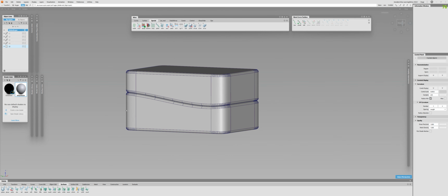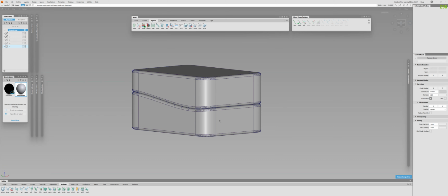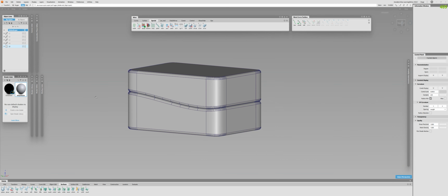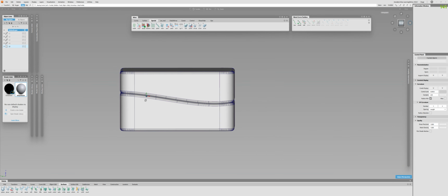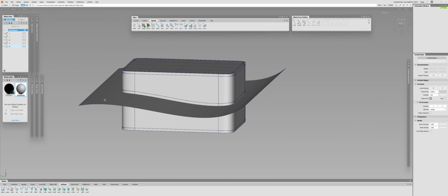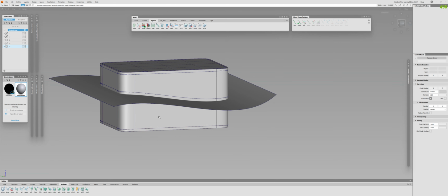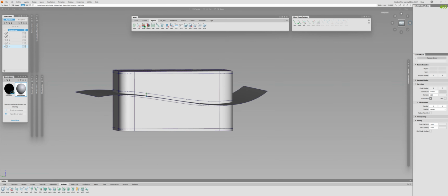Now sometimes you need a gap between them, and so there are a couple of ways you can do it. Well, first you can use, instead of just a curve, you can offset this and use the actual kind of solid geometry, or you can perform the cut as I did, and then after that just pick the curve which we built before, this one, offset this, and cut one of them, basically the top or the bottom part, and just use the standard trimming operations as you always do.